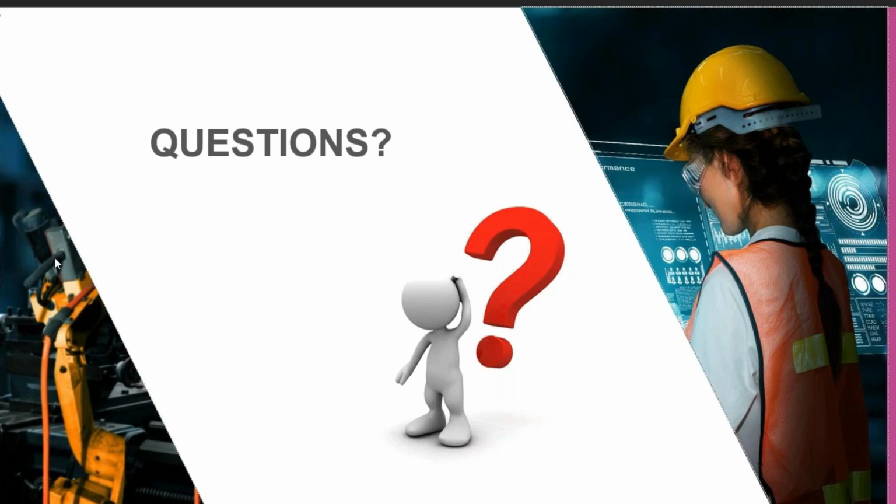Oh, Jason, I think you were asking about where I was cutting out the part using the revolve feature. I think the extension was going probably a little bit too far, although the extend probably would have failed. But basically, once you solidify that surface into the solid part, it then makes the cut. So that was basically the last step. But at that point, I just wanted to continue to show you guys what else you could do with the tools.